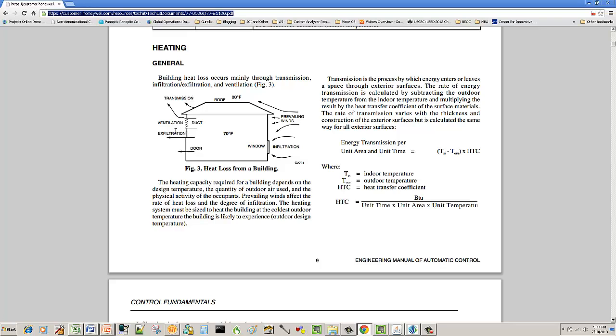Typically, a building is ideally wanted to be positive. What does that mean? That means that air is not coming in, rather air is going out. So if you open a door, you'd want to feel a slight breeze leaving the building. What does that do when a building's positive? Well, that's going to keep thermal infiltration, ideally from the winds that we're seeing, from different outside pressures, from coming into the building.